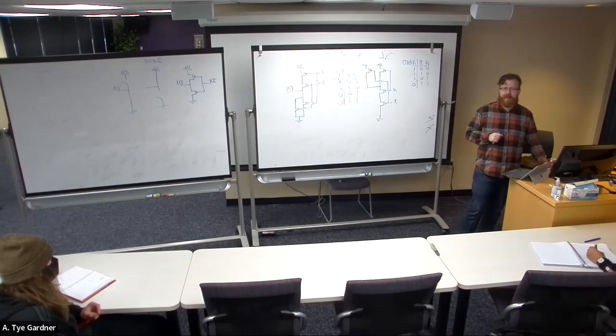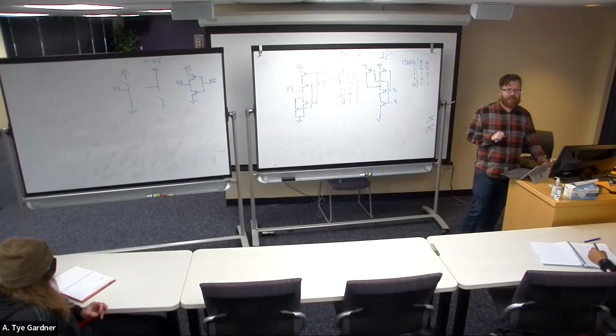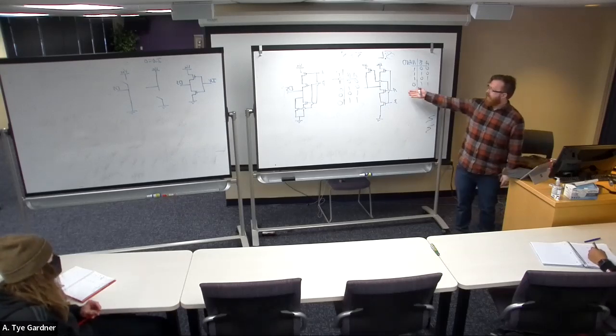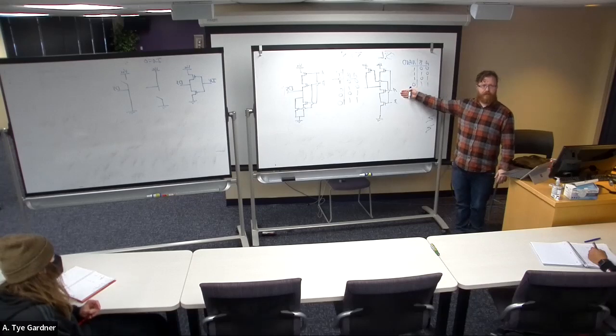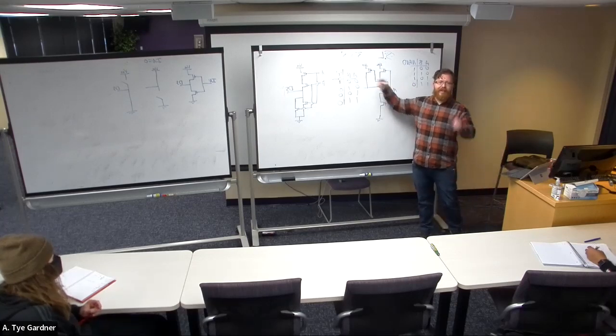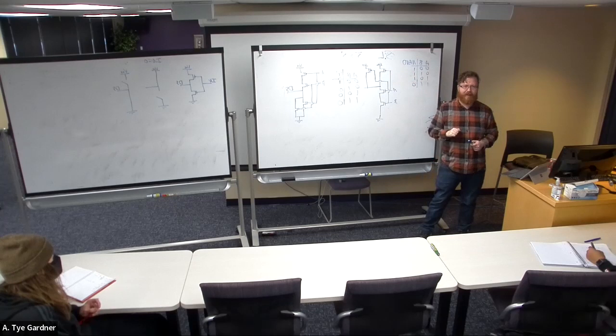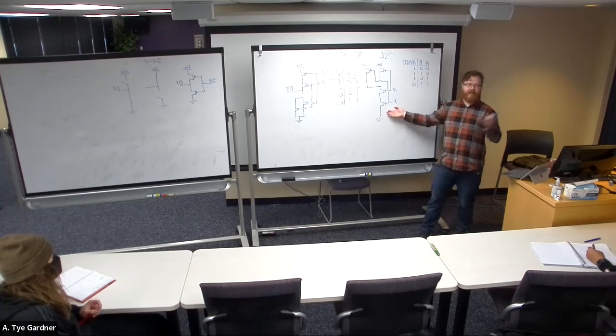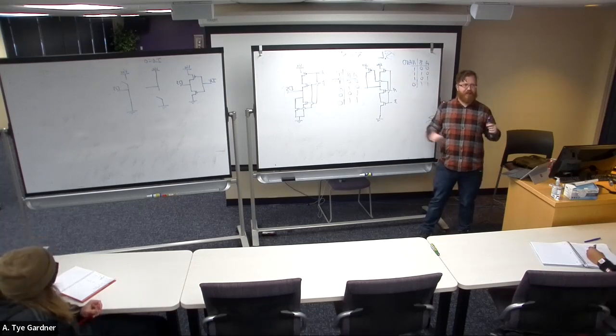Okay. Let's say I apply the same principle and now I want to make a 3-input NAND gate. What do I do? Just do, because NAND gets on the left, right? Yeah, this is NAND. Add one more in parallel, and one more in NMOS series. Exactly. We would have one more in parallel and one more, we would call it C, in series. And now I have a 3-input.